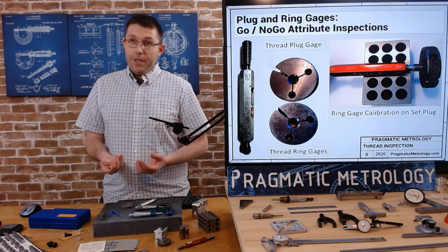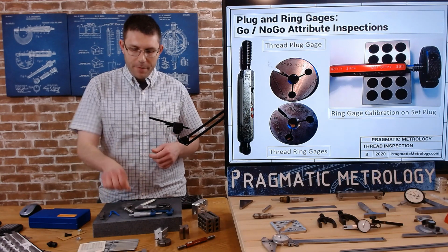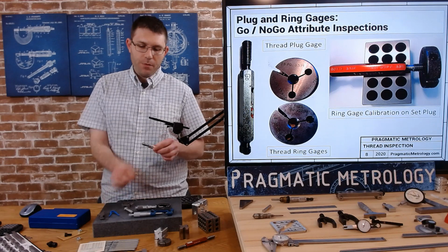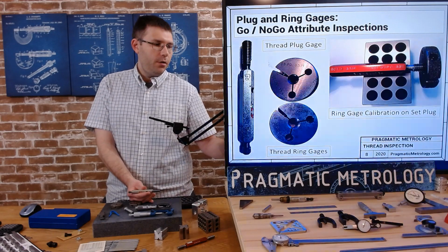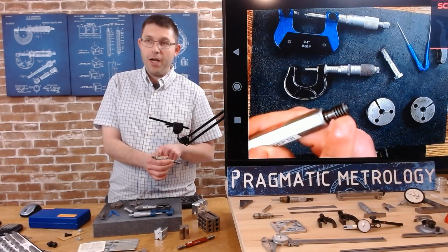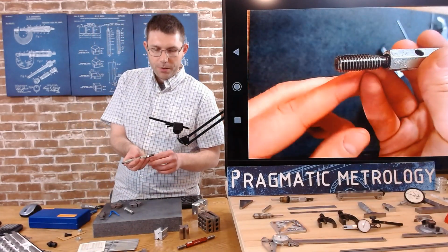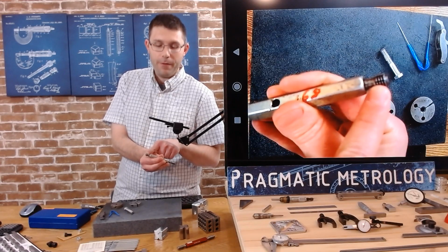Now, when we talk about how do we inspect thread itself, the pitch diameter, I mentioned we have some specialized gauges, and we have a thread plug gauge and we have thread ring gauges. These gauges come in Go, NoGo applications. So on a thread plug gauge, your Go side should go in the hole and your NoGo side should not. When you're dealing with a plug gauge, the Go side is typically longer than the NoGo side. That can help you quickly identify it.